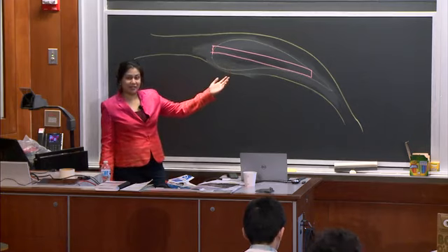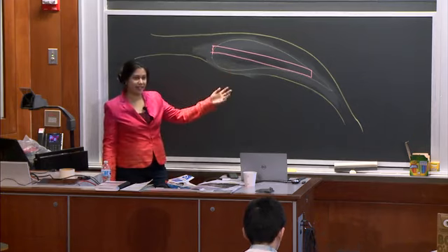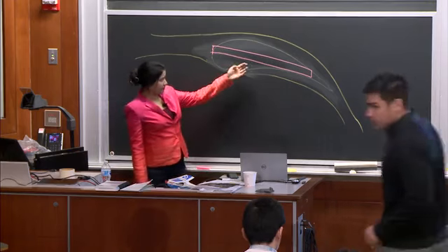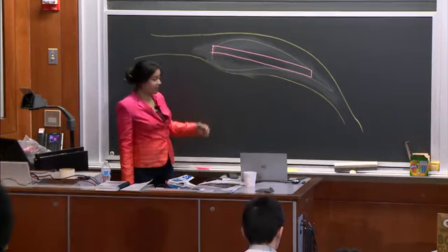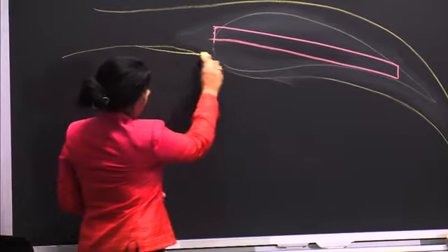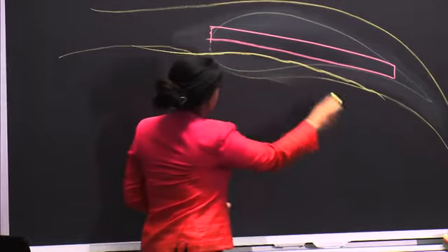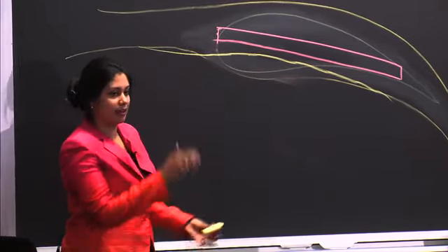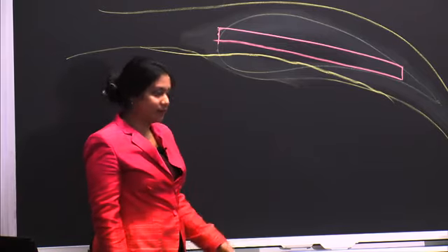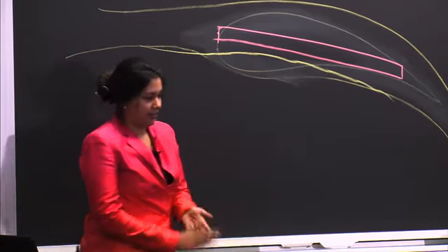Yet, a paper airplane still flies. So why is that the case? Again, remember the actual reason is that if this paper airplane is inclined, it is pushing air down. So air that's coming up is bumping into it and being pushed down. And therefore, as you deflect air molecules down, by conservation of momentum, the wing is lifted up. All right.